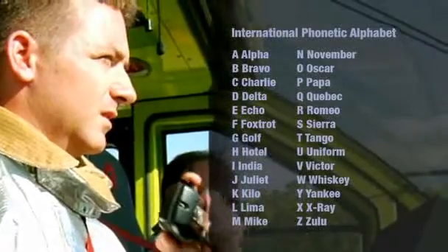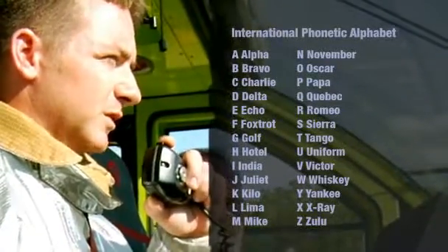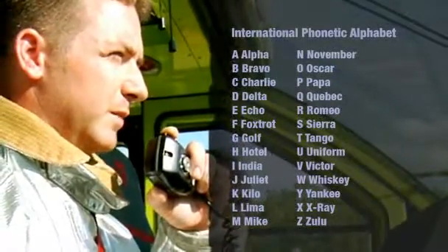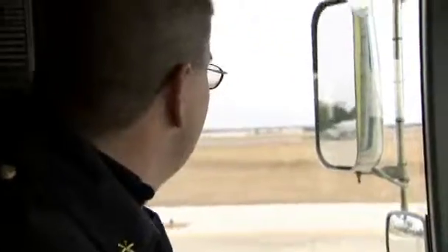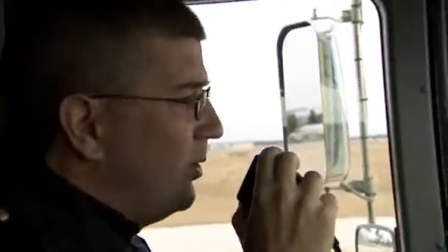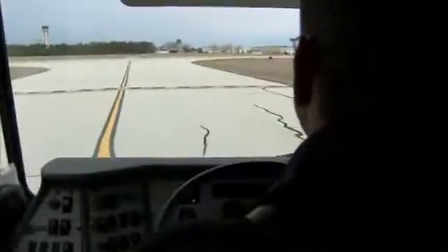Because many numbers and letters sound alike, airports use the International Phonetic Alphabet to communicate letter designations over the radio. For numbers, speak one digit at a time and pronounce the number 9 as "niner." For example, to refer to runway 29, say "runway 2-niner."